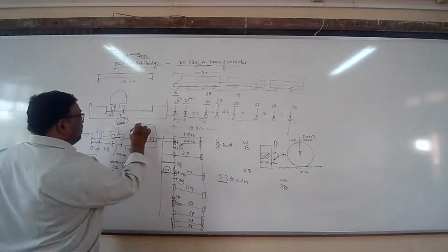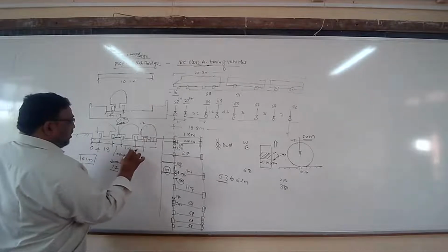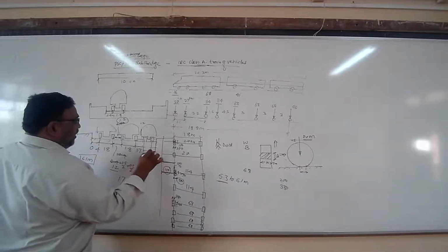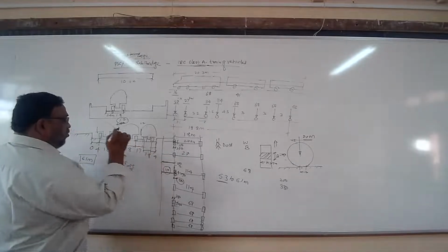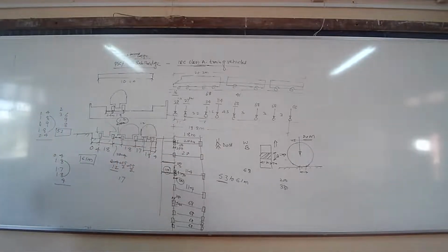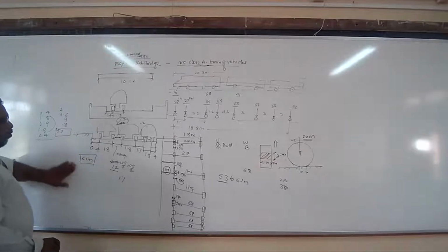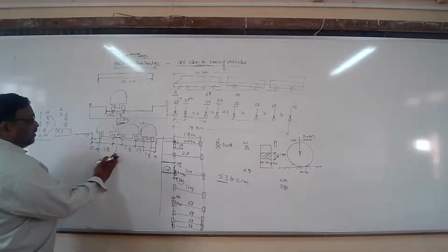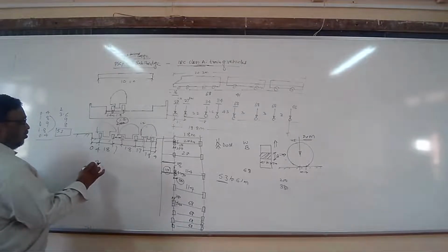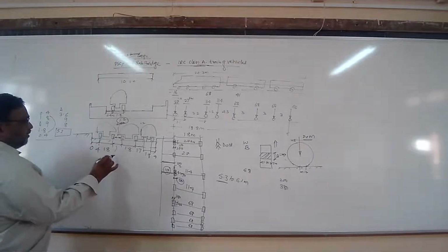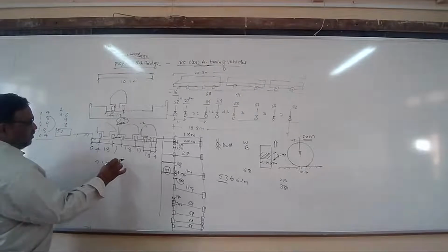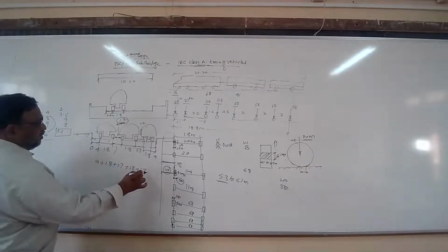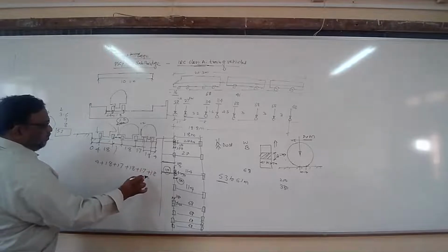Minimum clear distance must be 1.2 meter. So center to center distance must be 1.7. The center to center of this wheel is 1.8 and this minimum clearance is 0.4. So how much will get added to this? What will it be now? For 3 lane, minimum, कितना रहेगा? 0.4 plus 1.8 plus 1.7 plus 1.8 plus 1.7 plus 1.8 plus 0.4.